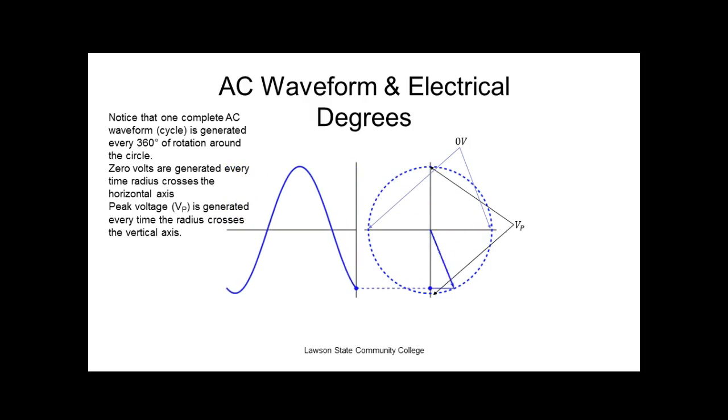One of them is a positive peak, the other a negative peak, but they're identical. If this peak is 100 volts positive, then this one is 100 volts negative. The negative peak, or alternation, is the mirror image of the positive. We call this waveform a sine wave.